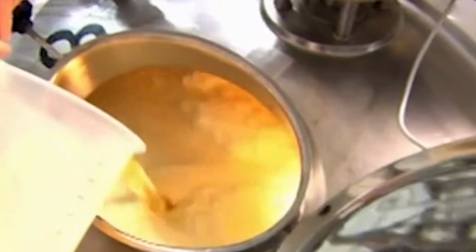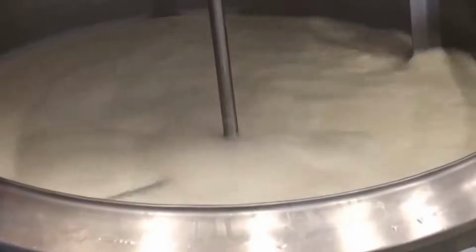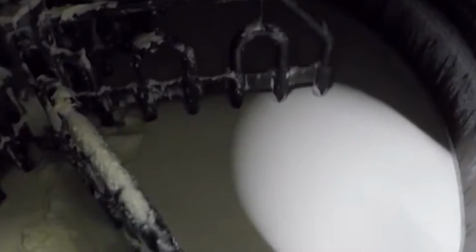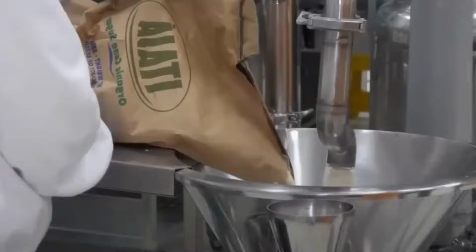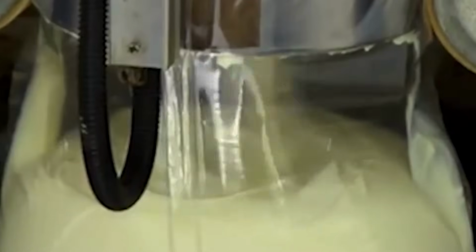Stabilizers and emulsifiers such as guar gum, carrageenan, mono and diglycerides, or cellulose derivatives are pre-blended into dry mixes and introduced using vacuum powder hoppers into blending tanks containing preheated water at 60-70 degrees Celsius. This temperature is critical for full hydration and dissolution. Agitation is applied using high-shear impeller mixers, ensuring uniform dispersion and hydration within 15 to 20 minutes.